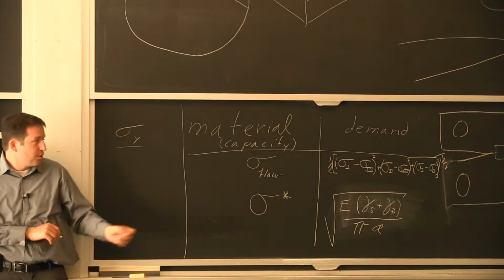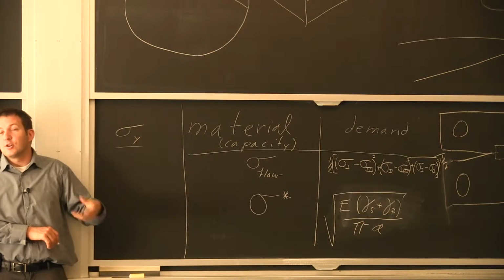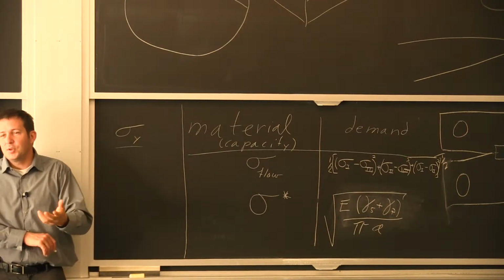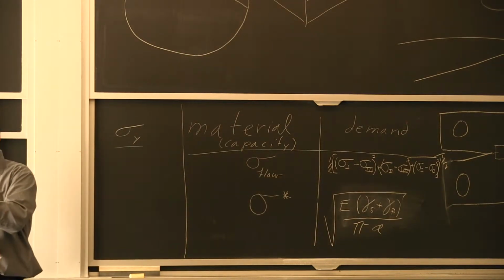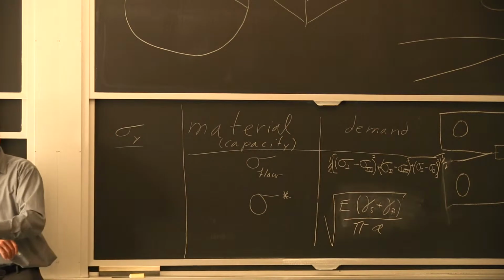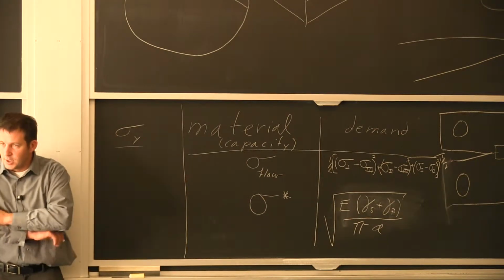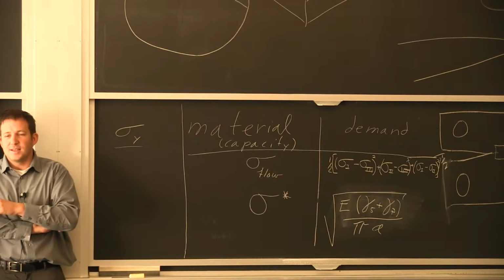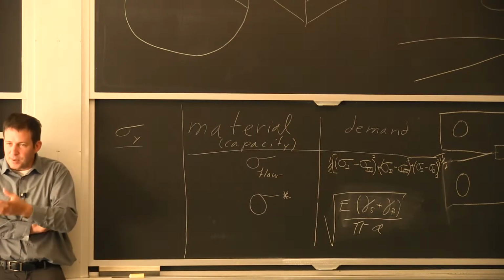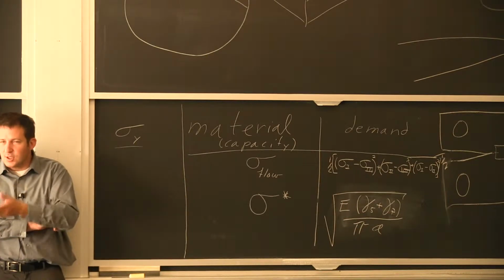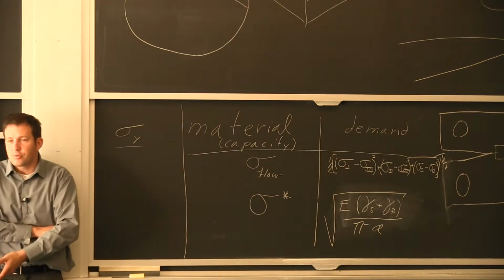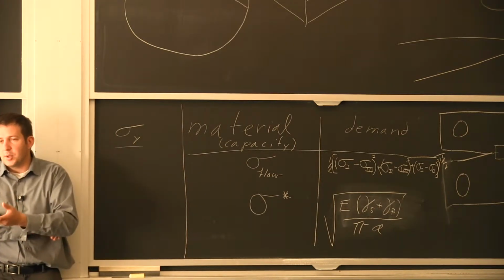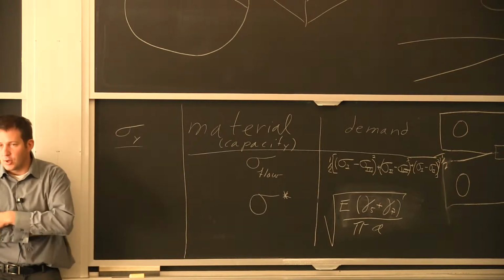As soon as you reach 33% of your yield strength, locally you're yielding. If you're yielding just a little bit and have enough strain hardening, it's going to become elastic again. And that's what happens sometimes with steel. So that's why it heals itself. You stop the plasticity in these cycles, and then you can continue to stretch the bonds up and down. You have very little movement of dislocation. It's just stretching the bonds, even in the area of impurities. And that's why you don't have an overall effect.